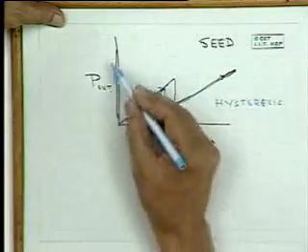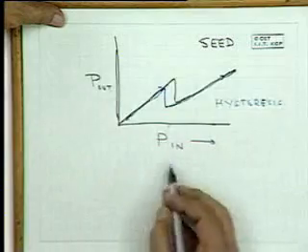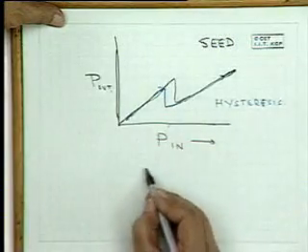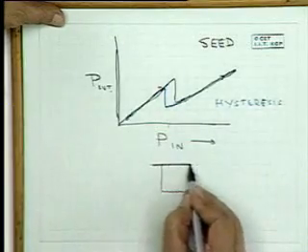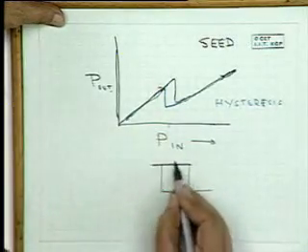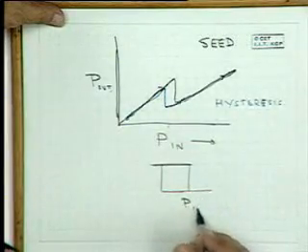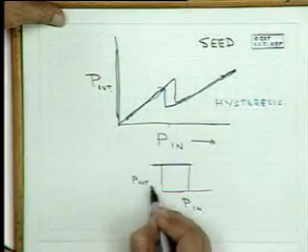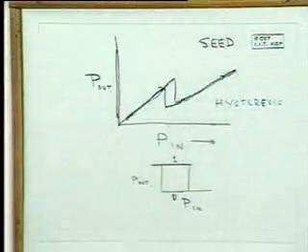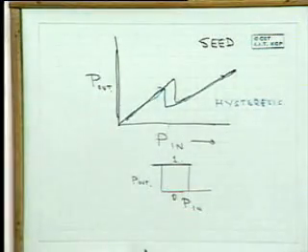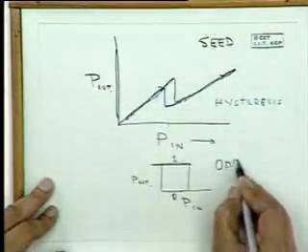Between the input power and the output power. So this is simulating what is known as a bistable device, a flip flop, which will have a characteristic something like this. Depending upon the input, it can have a zero state or a one state. In this region you have what is known as optical bistability.